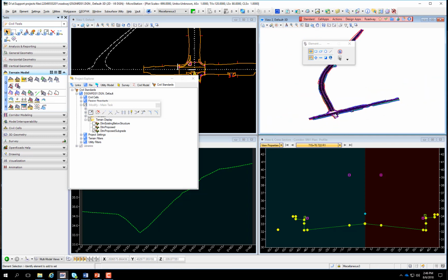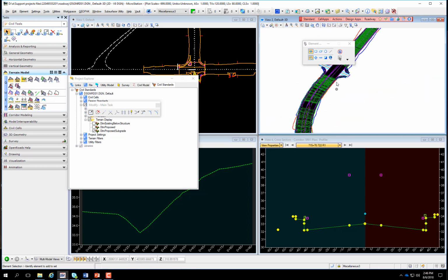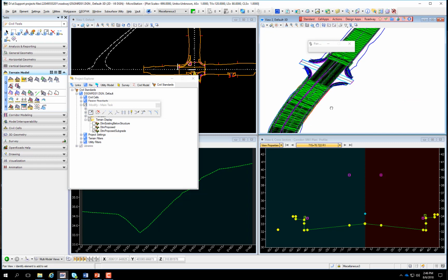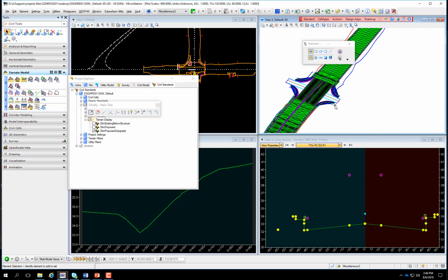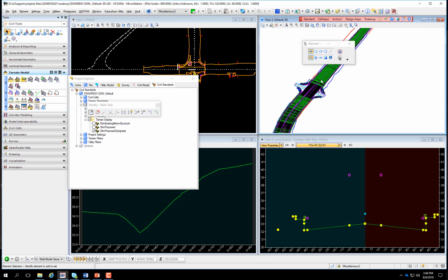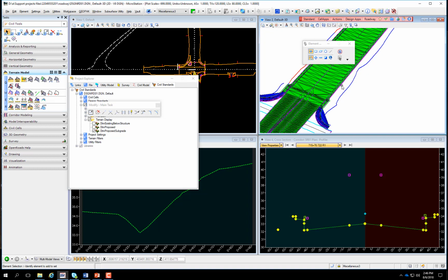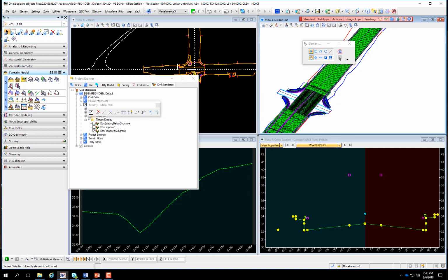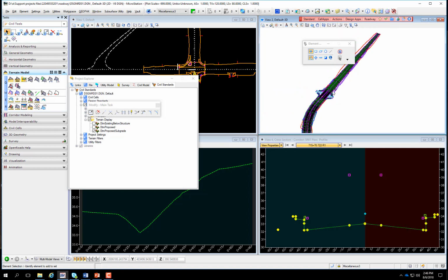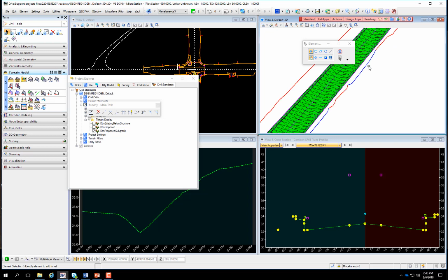But if you've got detail areas that are added to your corridor, then you'll have to go in and use this other method of using the break lines to create that. And again, for this subgrade surface, I didn't include my cut and fill line, so I would have to define those points on my template if I knew I was just going to use one alternate surface to define what this terrain was going to be.